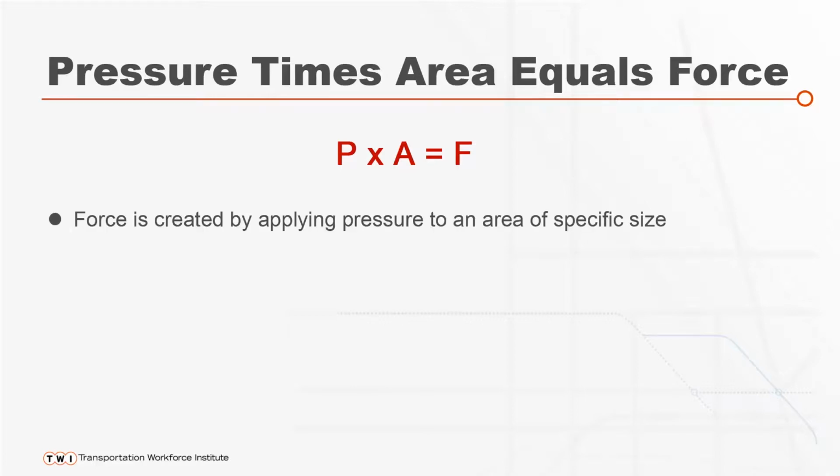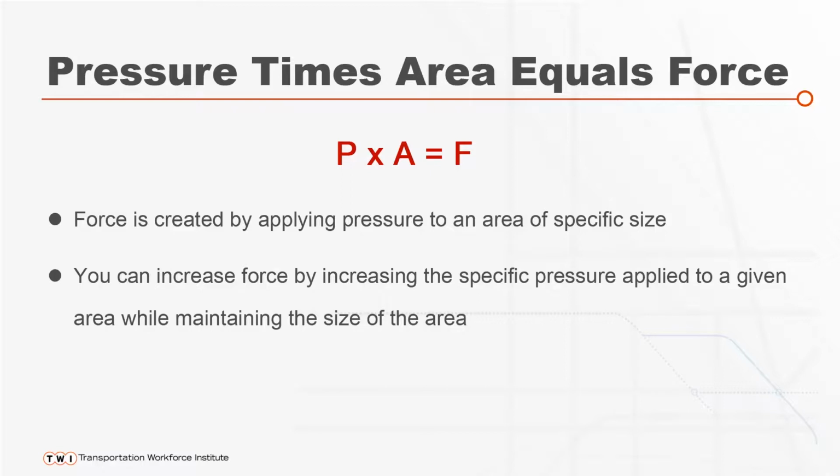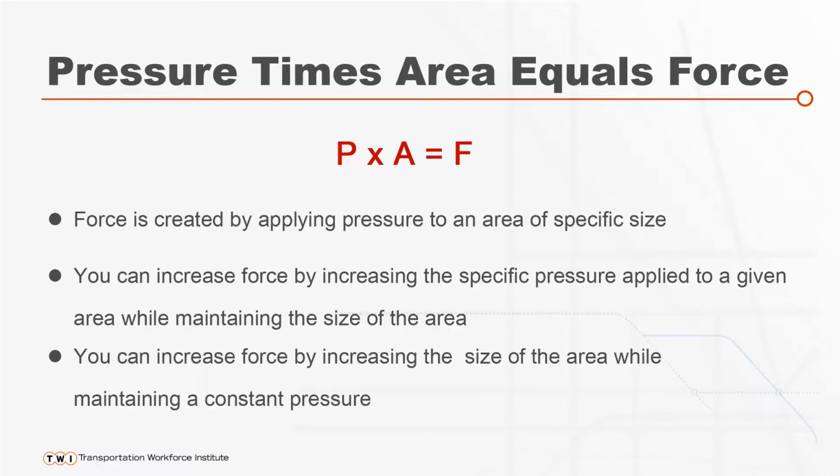Force is created by applying pressure to an area of specific size. Always remember you can increase the force by increasing the specific pressure applied to a given area while maintaining the size of the area, or you can increase the force by increasing the size of the area while maintaining a constant pressure.